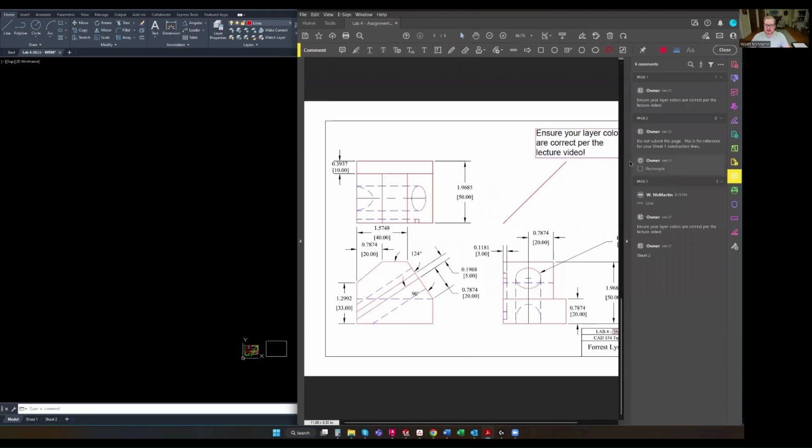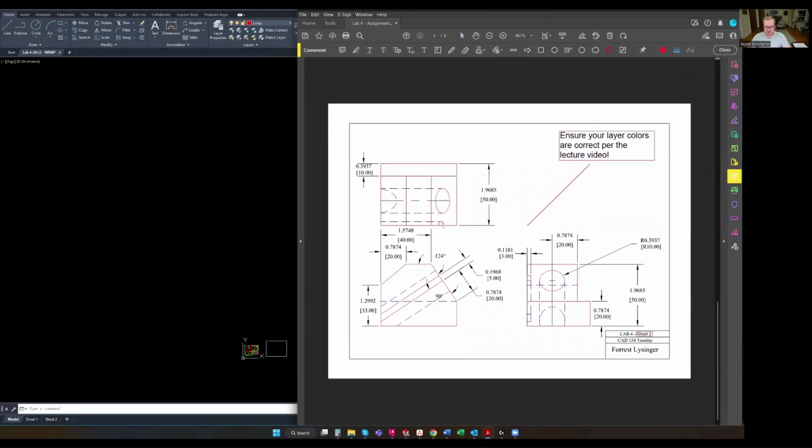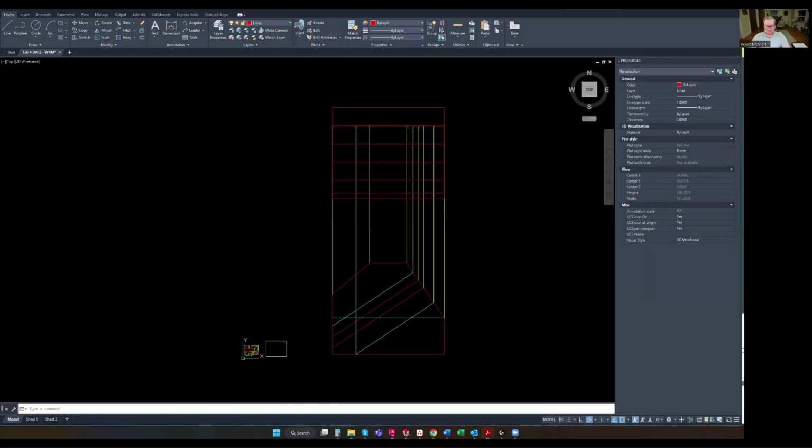And if I grab my multi-line tool here, we can see that this dimension right here for our slot, if we project it at the 45-degree projection line, comes from right here, where we have the 3-inch slot depth dimensioned. So that is where we got that information.